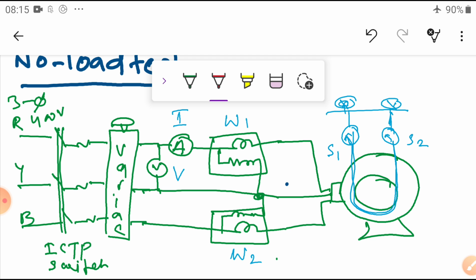So we take it, what has happened? R phase, Y phase. What are the precautions? This belt should be loose. So here the rotor belt should be very loose. No load on rotor. Now you know that M, L, C, V is connected. Here also M, L, C, V, the terminals of the wattmeter, are connected.